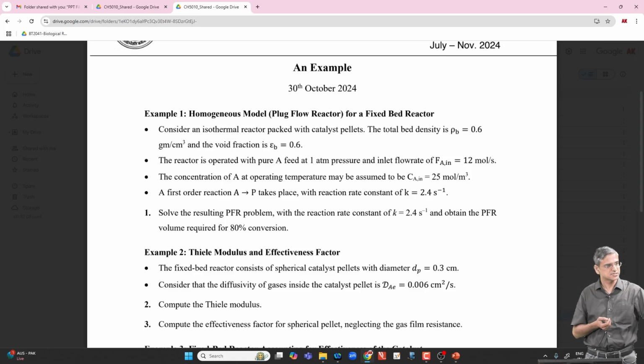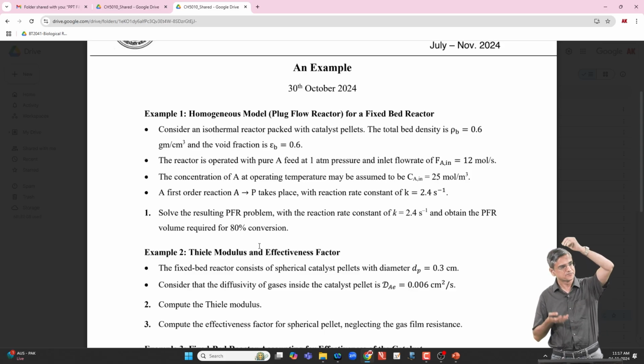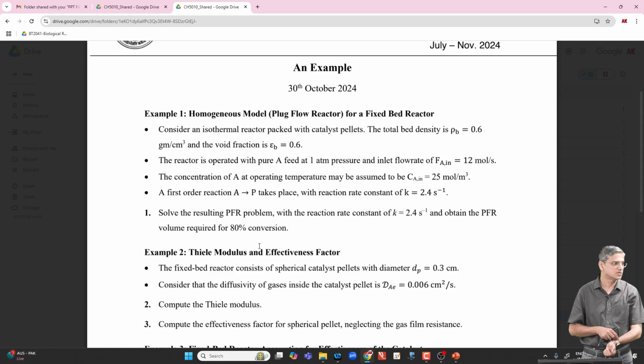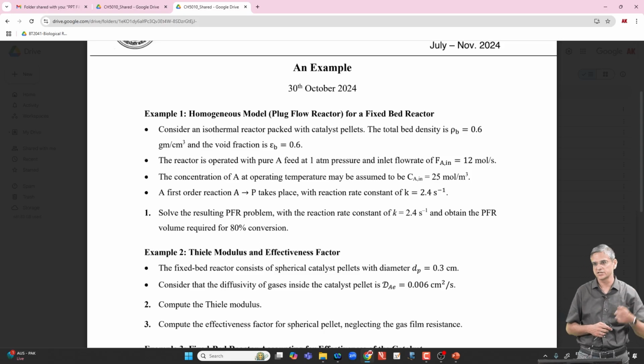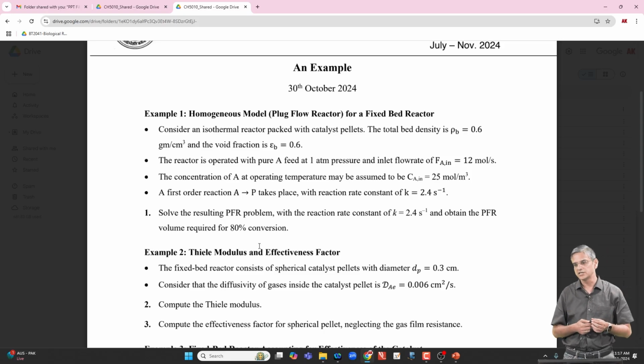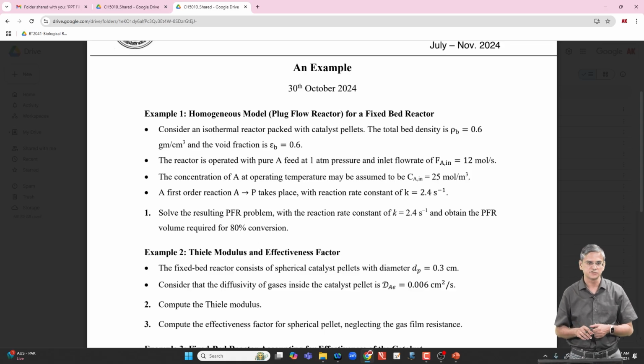Once we get the kinetics and put it in a reactor that we need to design, at that time we are usually not going to dilute the reactor unless we expect thermal runaway. Have you heard the term thermal runaway? Thermal runaway basically means that the rise in temperature is faster than our ability to take the heat away, and it can cause a significant rise in temperature, and then the internal catalyst material or internal structures can, for example, melt, and it can cause a dangerous situation. So you never want to go to a thermal runaway type of situation.